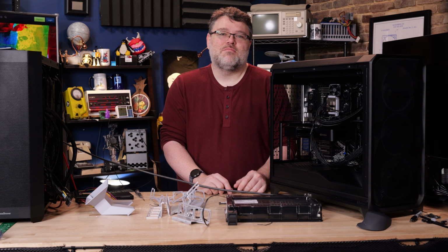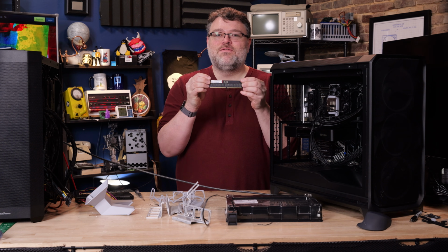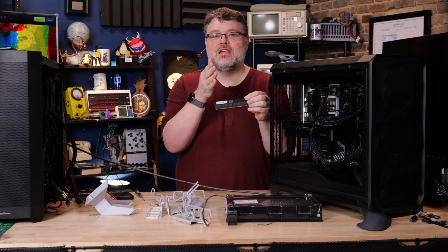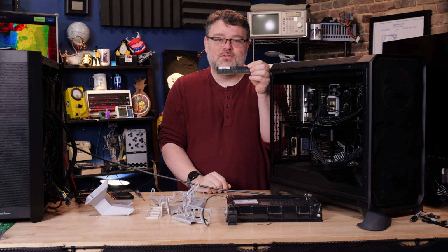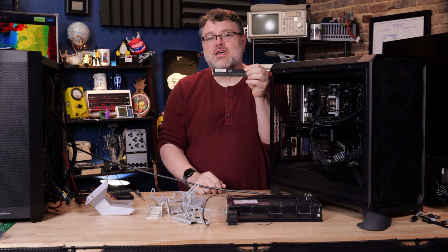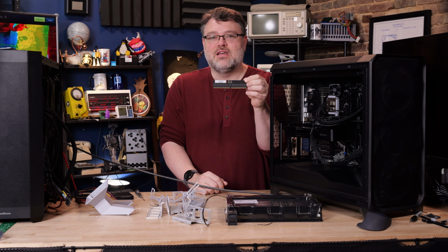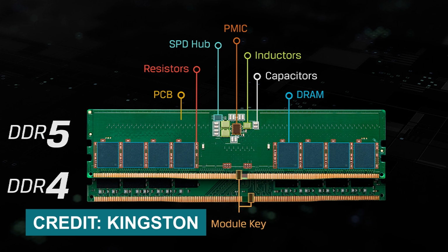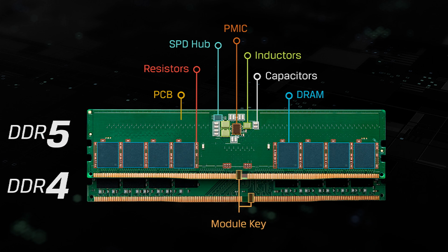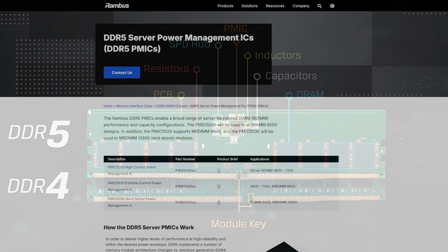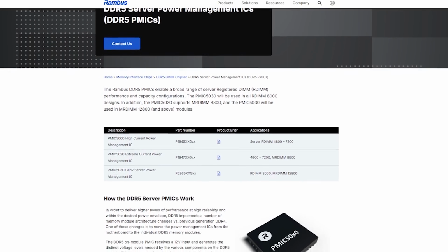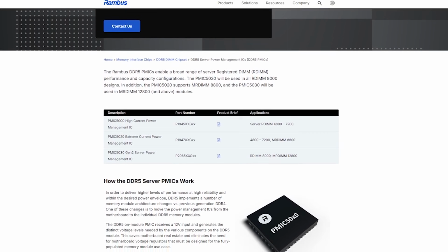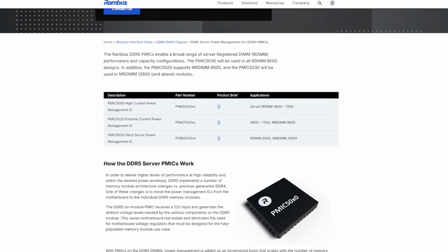It's important to understand that the memory on this DIMM is physically arranged in the left and right into those two channels. The halves are our two 32-bit channels, and they can more or less operate independently. And in the middle, we have our power management IC, the PMIC, and a registered clock driver, our RCD, that's here on the front. The part in the middle is the part in the middle because it's moving the voltage regulation onto the DIMM itself.